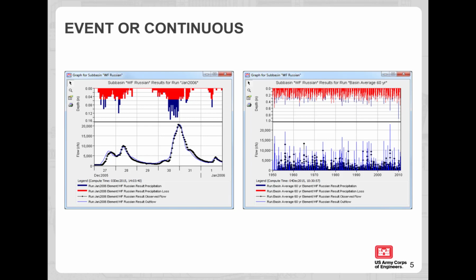A limitation that I will mention is constant versus variable parameters. In HEC-HMS, all but a few parameters are constant. A few things are allowed to change during the year. For instance, plant canopy can use an annual pattern. Some of our ongoing work is adding time variable parameters to some of the infiltration methods. Once that work is complete, we will probably look for other areas to apply time variable parameters.